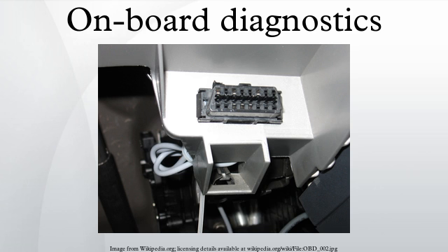Data field max 255. ISO 14230 KWP2000: pin 7, K-line, pin 15, L-line, physical layer identical to ISO 9141-2, data rate 1.2 to 10.4 kbaud, message may contain up to 255 bytes in the data field.